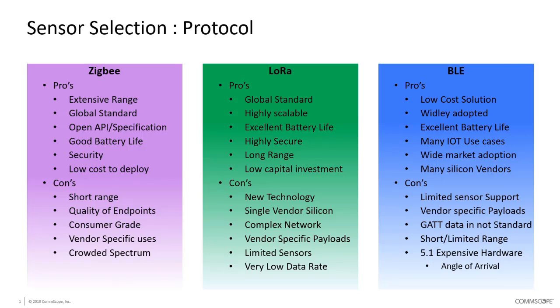Additionally, to do anything more advanced, you need to use what they call the GATT profile. The problem with the GATT profile is, if you're a lock manufacturer who is building an online door lock, you control all of the information in that GATT profile. So people can investigate and look at it, but all of the data is mapped into fields within that payload, which as the developer you understand, but anybody else looking in from the outside doesn't. So it really is very much a requirement for more complex devices to be working together with the back-end service or the network integrator and the device.